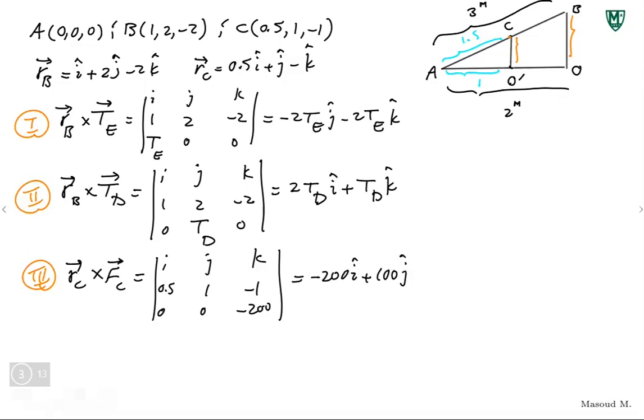All right. So now we have all the components represented in Cartesian coordinates. What we were trying to find was the summation of moments about point A. We said it should be equal to 0. Now I have the components, so I just sum up components and write them based on their direction, X, Y, or Z. Let's write the I component, J component, and K component.